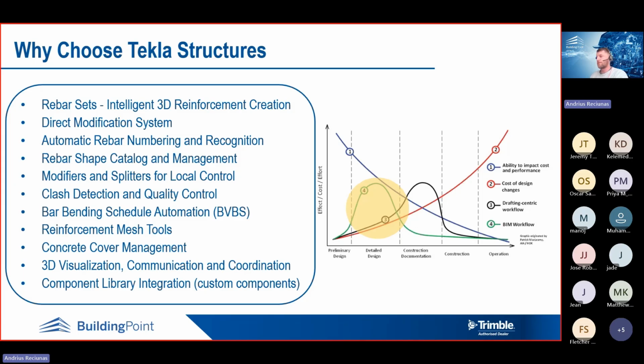And the last one is probably component library integration, which in Tekla words we call the custom component. So if it's not there, you can build your own tools. And if something's missing out of the in-the-box solutions as well, for those of you who don't know, there's Tekla Warehouse, where you can download any available application that someone else created, or even we created, or even different regions of Tekla Structures created, and you can download and use those, or even use third-party applicators whose business is solely creating Tekla Structures components.